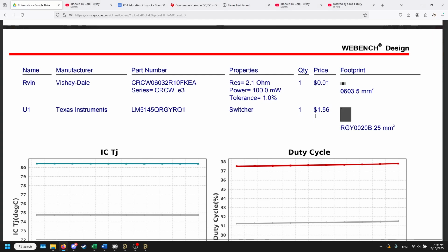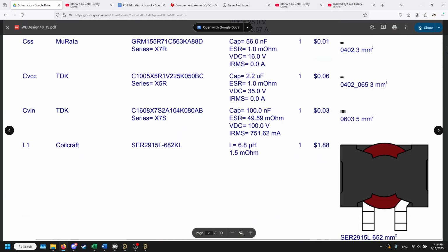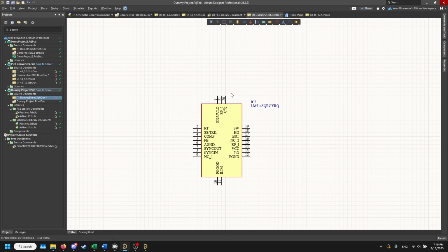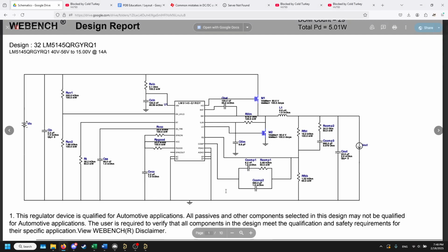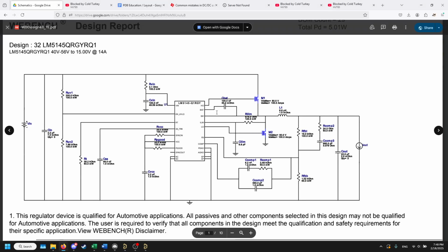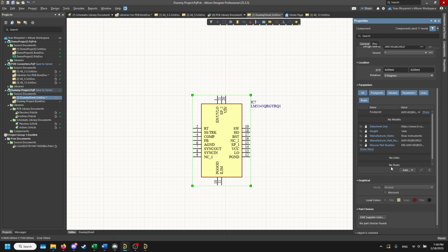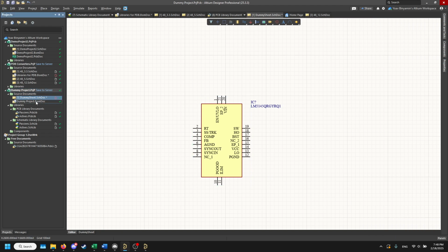The second thing is that if you go all the way up, you'll see that the pinouts is very different from what's here. It doesn't have this at the top and at the bottom. And so another difference is that if you go into this, you'll see that there are actually no supplier links put in. So if you wanted to make this into the bill of materials, then you wouldn't have any supplier links to put here. So I'm gonna go into the bill of materials and show you how that's gonna start looking like.